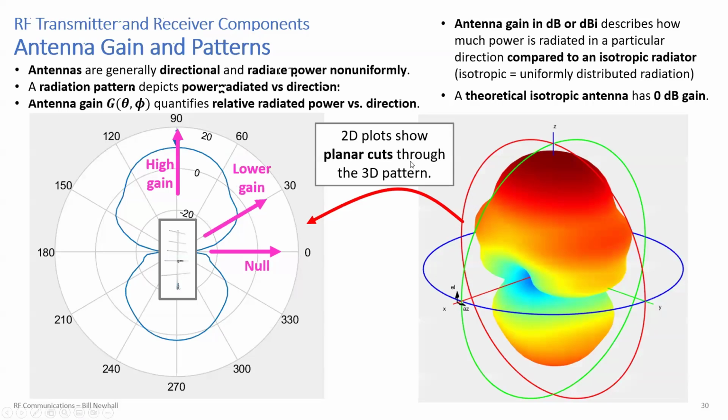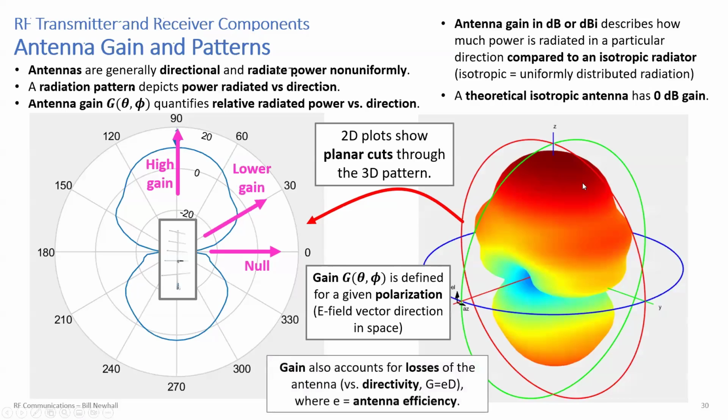So you can look at these three-dimensional diagrams and see the true radiation pattern, the power versus angle in spherical coordinates. We usually use these two-dimensional patterns. They're a little easier to interpret, in sometimes what we call the principal planes. So you'll often see two-dimensional antenna patterns. Antenna patterns describe whether an antenna is directional, in other words, it radiates most of its energy in primarily one direction, or if it's isotropic or mostly isotropic, if it radiates its energy kind of in all directions equally.